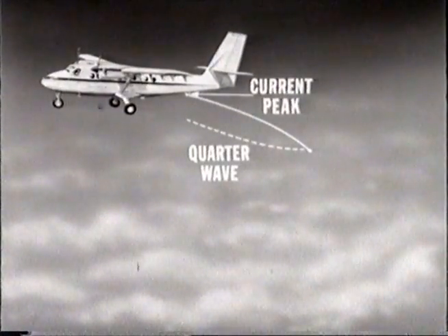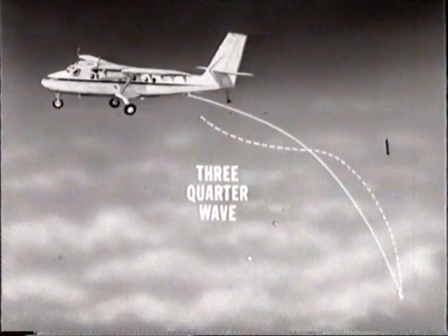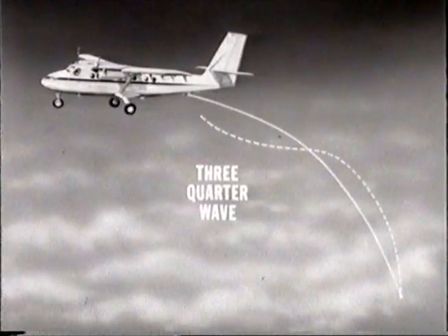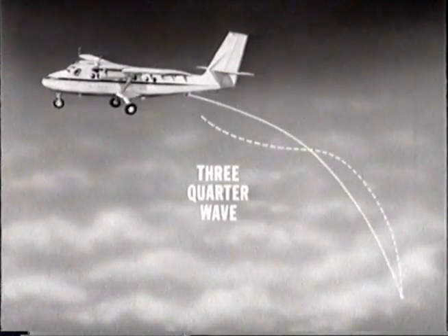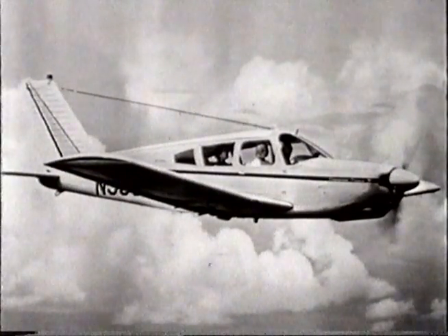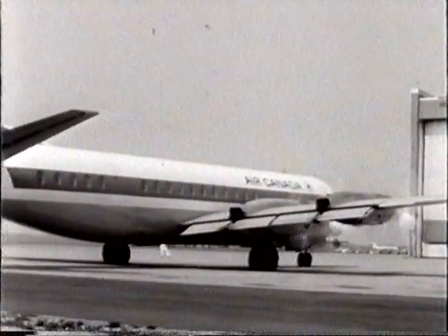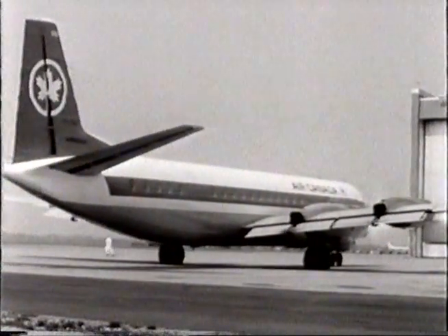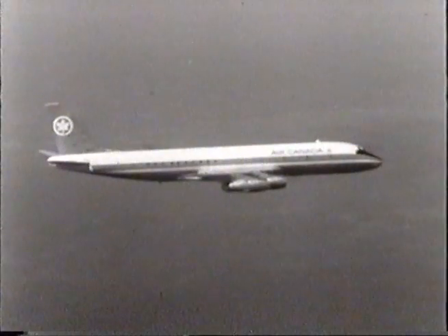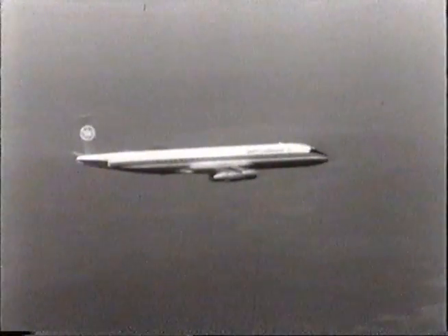In early days, the slow-speed aircraft were equipped with exterior antennas, such as the trailing antenna. The wire is paid out from a reel inside the fuselage. Usually, this antenna functions at the 3/4 wavelength. And the fixed wire antenna, stretched along the length of the fuselage or on the underside of the aircraft.